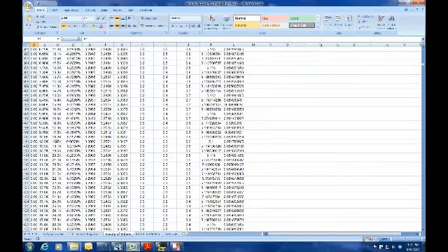So if you want to get a little bit more tolerancing on your output, if you want to be a little bit closer to your ideal 3.3 volts in this case, you're going to want to choose a 10.2, 18.7, or something else that gives you a better tolerancing on the output. And over here we can see the tolerance from the voltage divider over temperature.